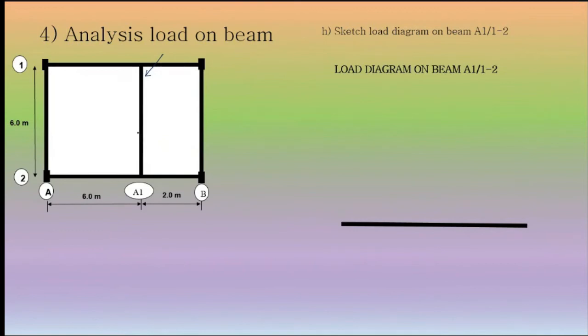Just now we just identify the types of these two panel slab, right? So the left one we got two-way slab. Because this slab is square slab, so all these four beams will support the load from this slab equal, in triangle shape.